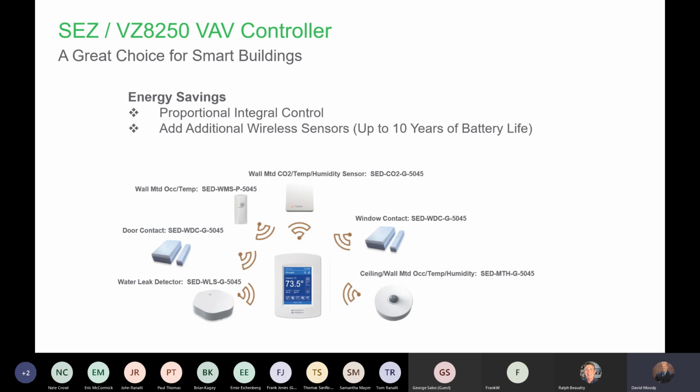And this is where I talk about the ZigBee / Wi-Fi. What's important to understand when you buy one of these is that there's only one expansion slot on a room controller. That expansion slot can handle a CO2 module, a ZigBee radio module, or a Wi-Fi radio module. If you buy a room controller and you want to talk to field devices, you have to have ZigBee, so you put the ZigBee module in it.